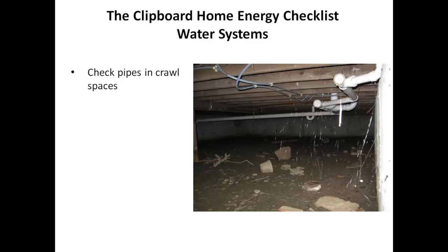If they would have had that floor insulated, then it would have been colder down there sooner, and the pipe would have been frozen and broken sooner. So the lesson there is, make sure your pipes are well protected by being up against the floor with the insulation on the outside or the cold side, so that that pipe stays warm.